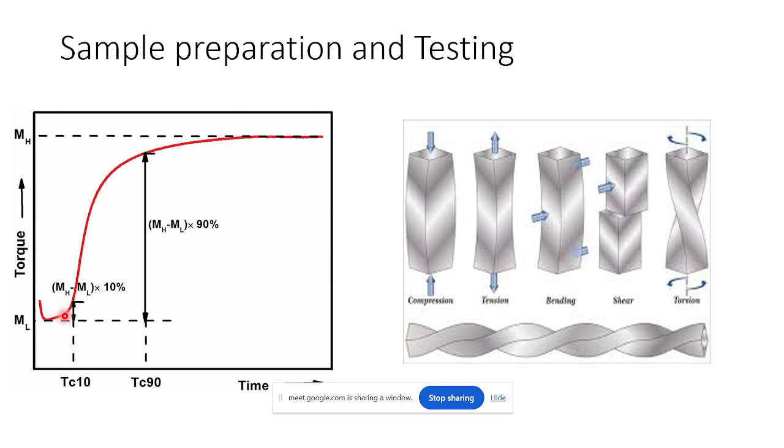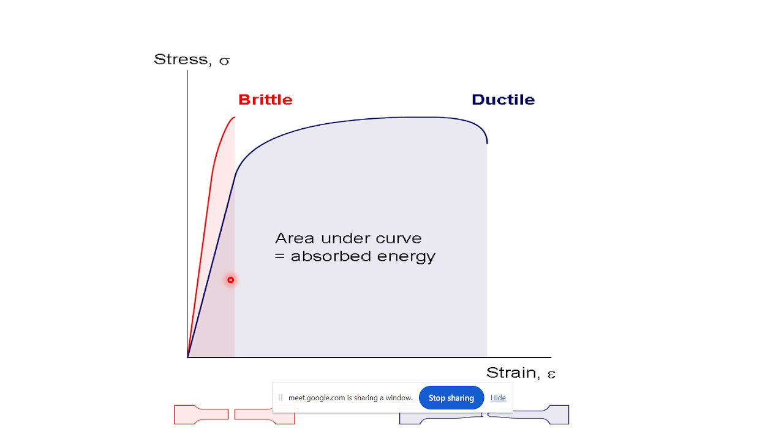the curing time, that is TC90, and also from when the curing starts, that is the TS2 value, that is also very important. Based on that you can set the different temperature during calendaring or during building, and also when it will ultimately be cross linked under press, what will be the temperature or what will be the rate of increment of your temperature.